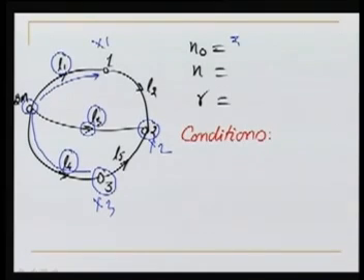We need only 3 observations in order to solve this problem, but our solution is a unique solution. We do not know about errors. We have been talking about the significance of redundancy. There is no redundancy in the observations in this model.